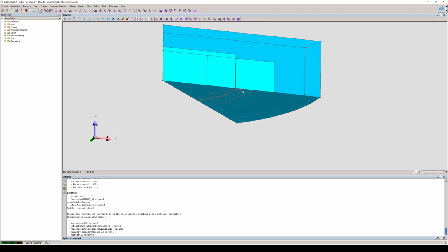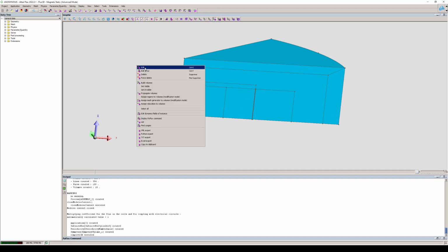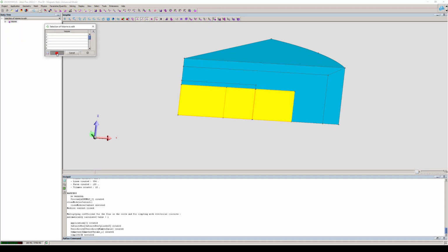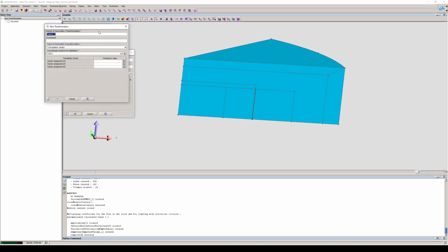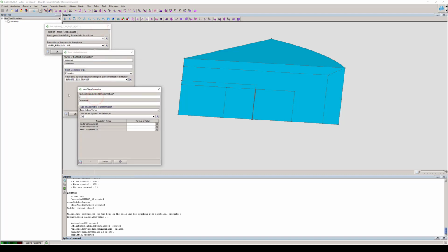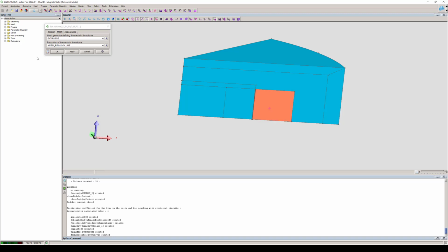meshing. So what we can do in order to define an extrusive mesh is to select all the volumes. This one can have an extrusive mesh. So I could go ahead, mesh, create a new mesh generator. This one will be called extrusive, and it will be extrusion type. I need to associate a transformation with this extrusion. So it's, let's say, Z extrusion. And it needs to be the same length as the extrusion I made in the modeler. Okay. So I create the extrusion, I use it in the extrusive mesh generator, and then I assign this extrusive mesh generator to these volumes.